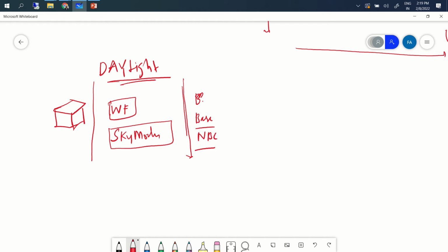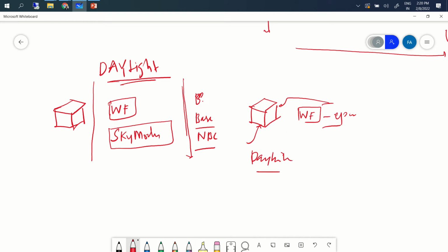Okay, so in the last slide I showed you can do a model of your house, identify the sun path, and so on. If possible, try taking the weather file and keep the EPW file with you so that we can do some analysis further on. So we'll do one analysis, for example how do we do daylight analysis for a particular room in a simple manner, the way we have seen from morning.